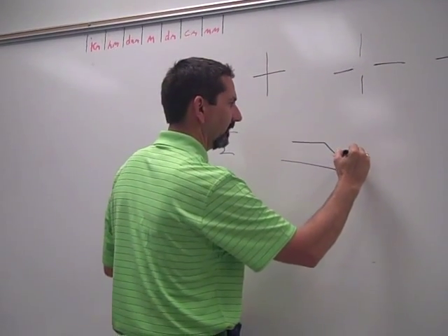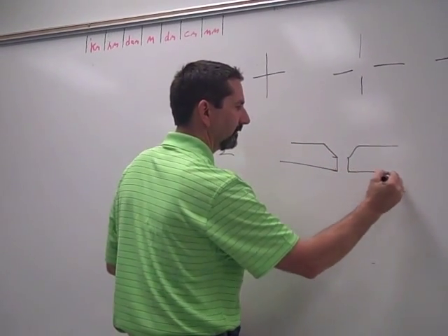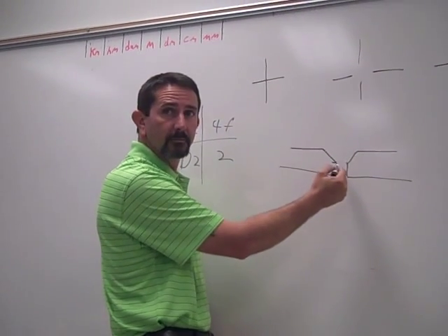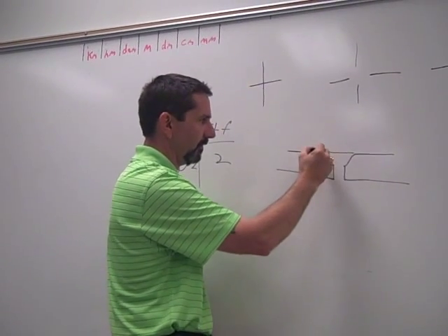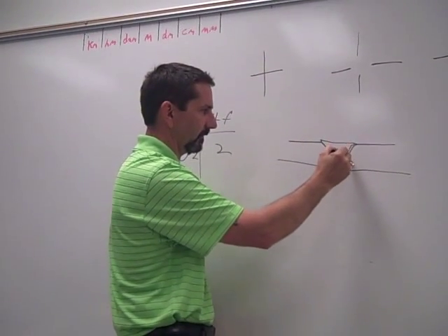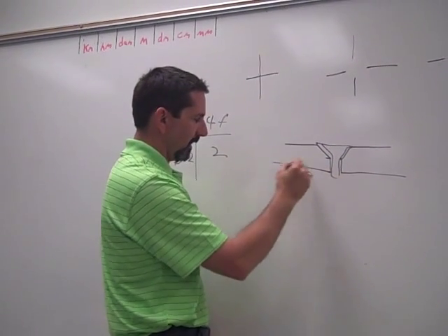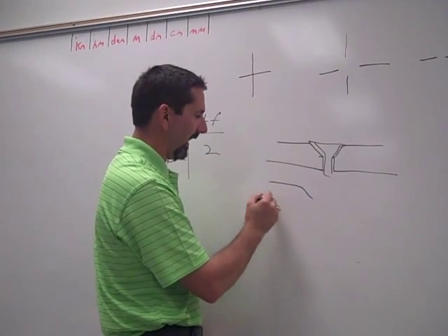It's a countersink. Usually 82 or 100 degrees. Material is removed for the fastener to set flush in the hole. It's driven. In a dimple, material is not removed. The material is bent mechanically.